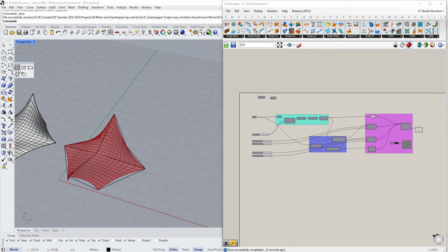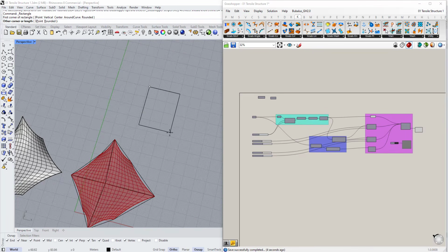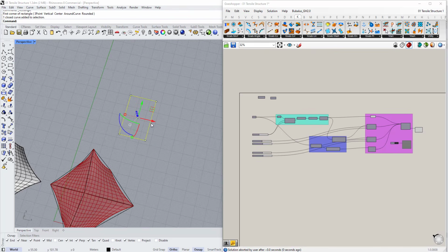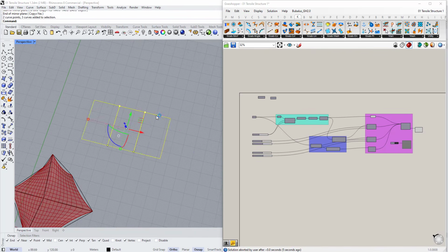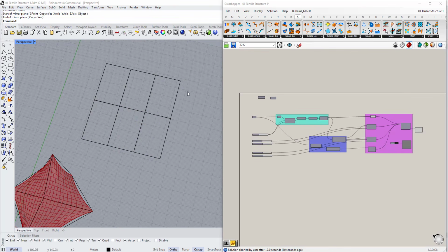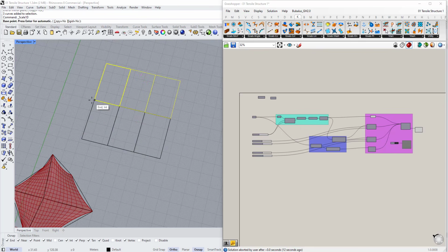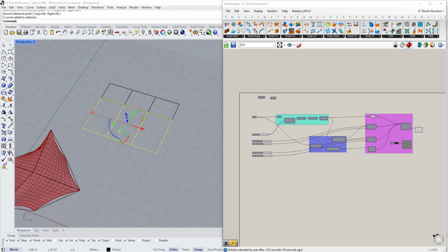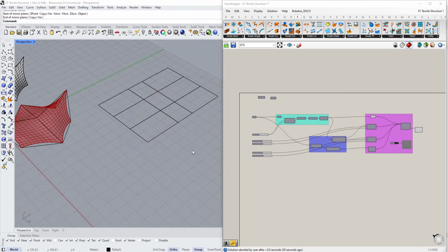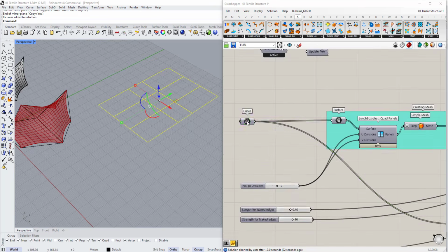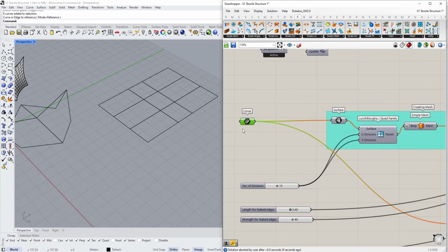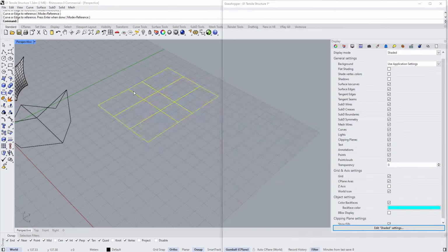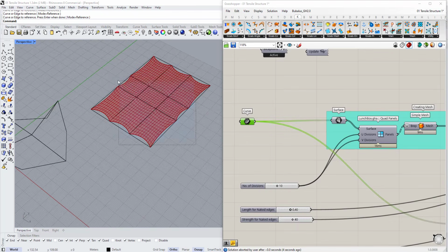So I'm going to create maybe more rectangles. Let's create something like this. Type mirror, the mirror here, another copy here, another copy. Select all of this, right click to bring the command again, create a mirror here. For this one, I'm going to scale them a little bit, so use the scale in one direction, and maybe another mirror, but here at the midpoint. So now select all of this, right click and choose set multiple, select all of this. So we have our shape.